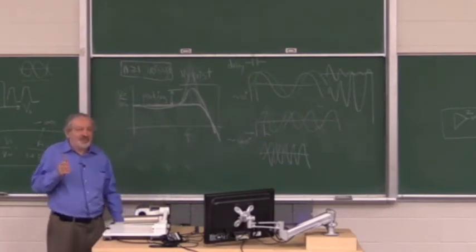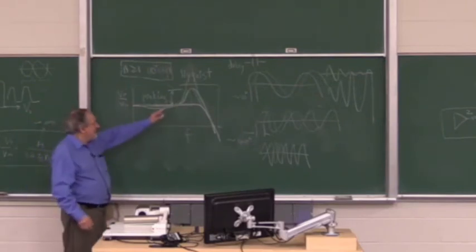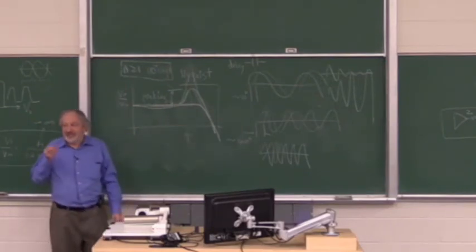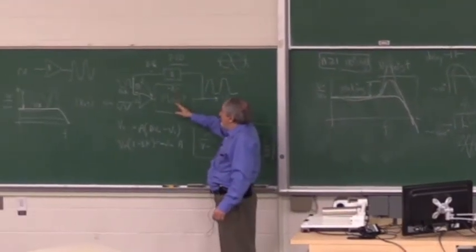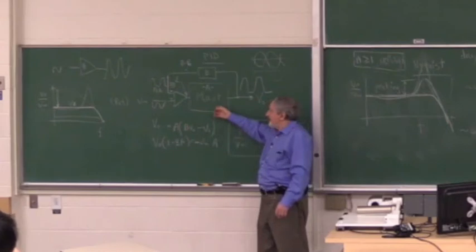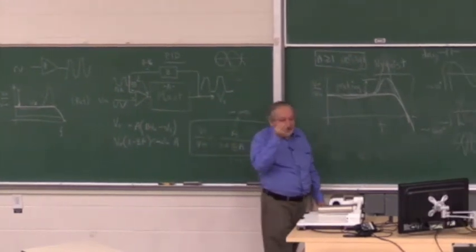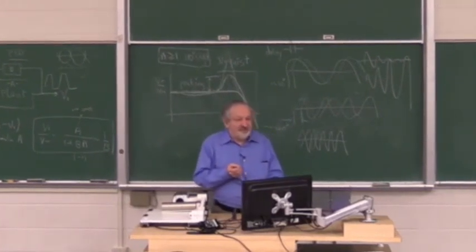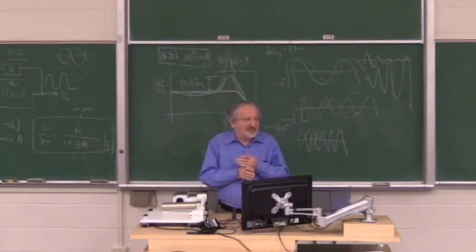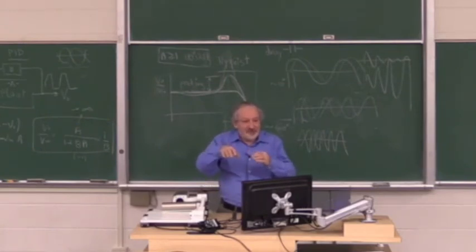The thing which kills the stability of servo systems is a delay. The delay in the sensing, or delay can happen inside here too. Somewhere there's delay, usually in the plant itself, because the sensor can be made fast. So the delay causes phase shift. The phase shift increases with frequency. So there's two things fighting each other. The phase shift gets worse and worse with frequency, but the gain drops. So if the gain is still high enough when the phase shift is near 180, it will oscillate.